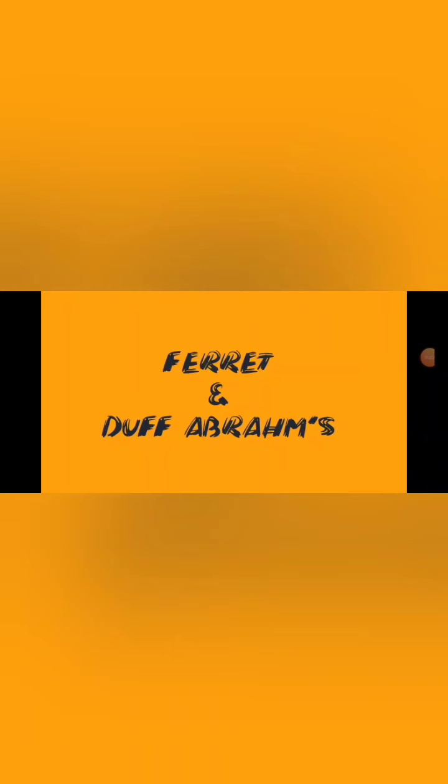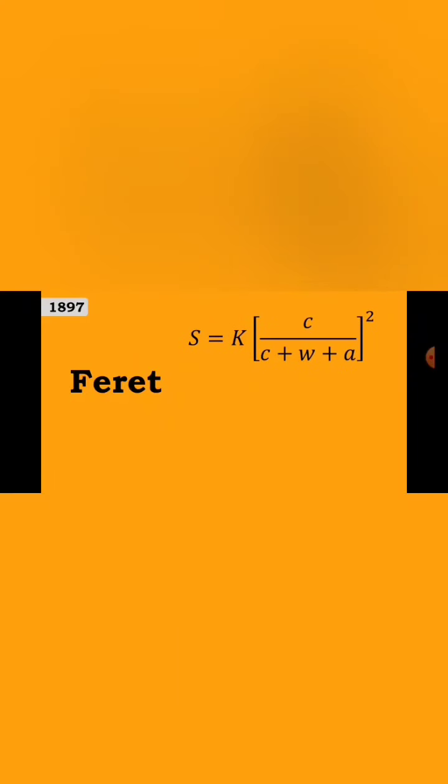Feret and Duff Abrams explained the relation between the water as well as the cement paste formation. Feret explained the attainment of the strength of the concrete by the plasticity law. He explained it with an equation where S equals K times the quantity C divided by C plus W plus A, whole squared, where C is the volume of cement, W is the volume of water, A is the volume of air, and K is a constant given by Feret.